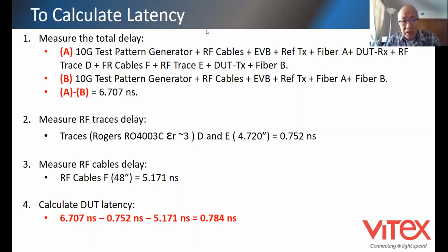There's another question, is the process the same for PAM4? That's a good question. Yes, so if you are familiar with PAM4, the PAM4 eye is measured every time by an equation averaging all three eyes together, all of the rise times, all the fall times, all the different levels together, right?